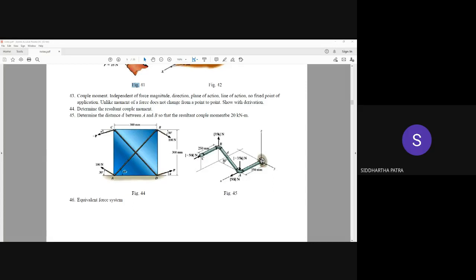What is coming? Sorry, sir. The net couple moment along the x-axis is 17.5d root 3, along the z-axis probably 25d root 3, and along the y-axis possibly 25d. Yes. So the magnitude of all of that should be, let's say, 20 Newton meter.